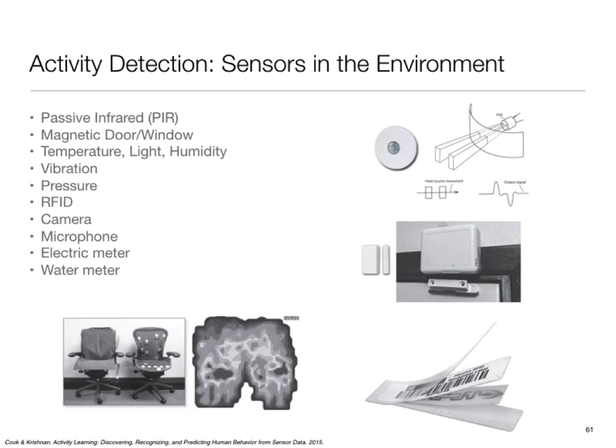To convert them into digital, you somehow convert them into voltage or current, which is what your A to D converter is going to sample. And then you have a number, but that number corresponds to that physical quantity. And then you rely on some sort of a physical model or some other data-driven model to relate it back to something of interest, right? So for example,